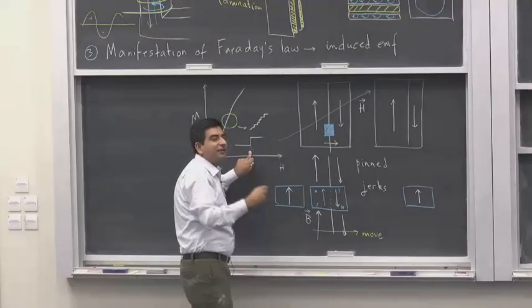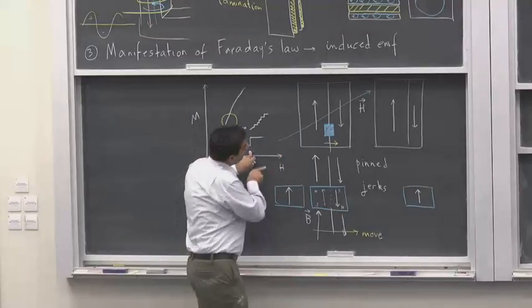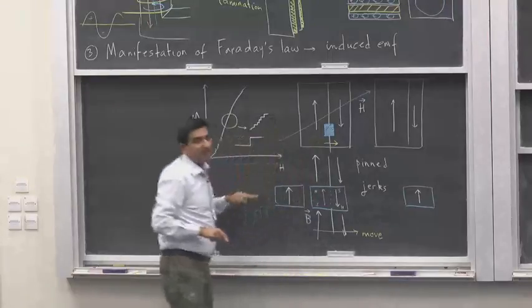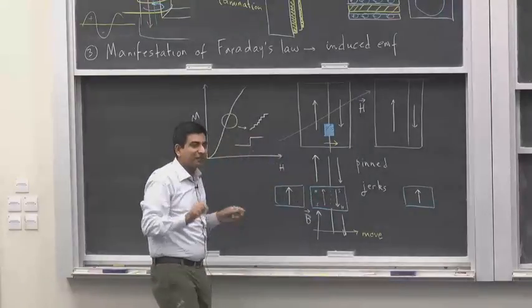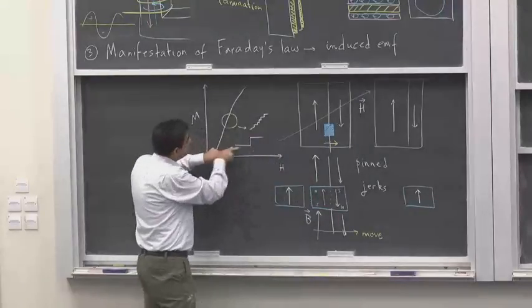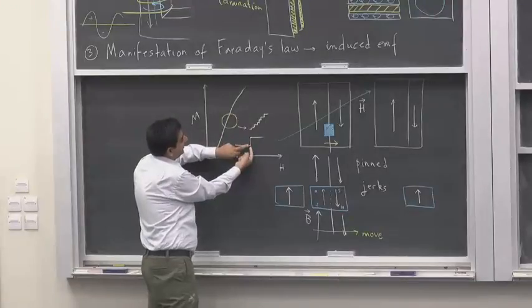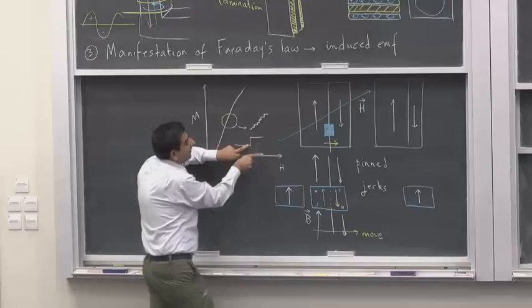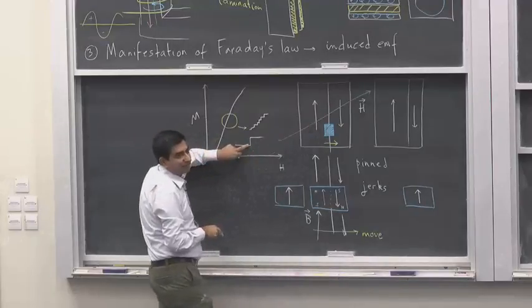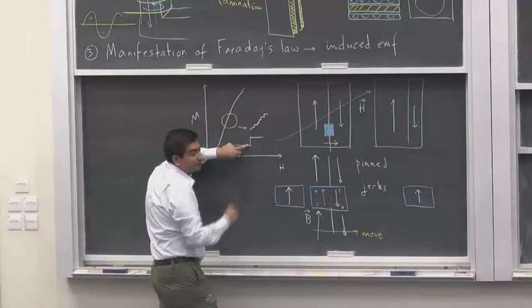So the domain wall just moves on because it is being dictated by this externally applied field. The impurities are playing their minor role and they can arrest the motion of the domains only to an extent. Suddenly, the magnetization just goes up in response to this H and the domain wall moves on.